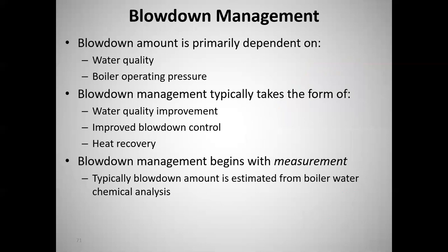So the utility companies, the TVAs of the world, operating at 1,800 pounds or 2,400 pounds or whatever, have to have extremely pure water. We take water and drink it out of the water fountain, right? Well, we used to, until they disconnected all of them. You go home, get a glass of water and drink it. Well, you're drinking all that crud. You can't put that in a boiler, but you put it in you, works just fine. So these boilers are much more delicate, and that water has to be cleaned up.